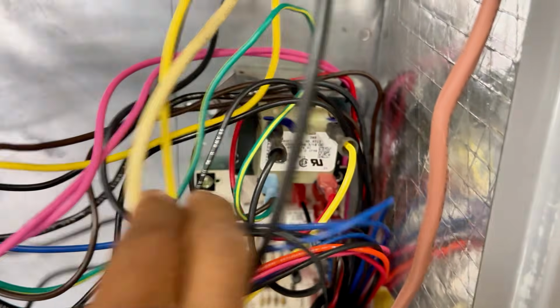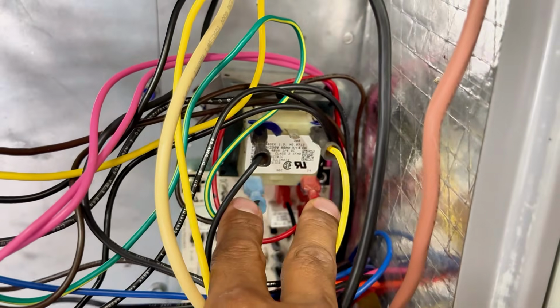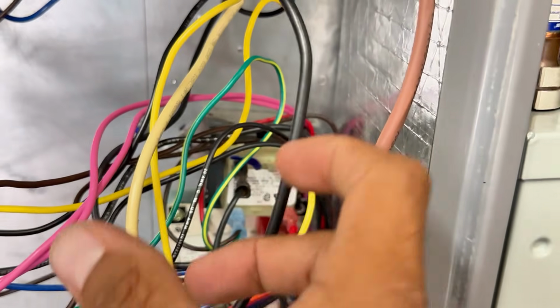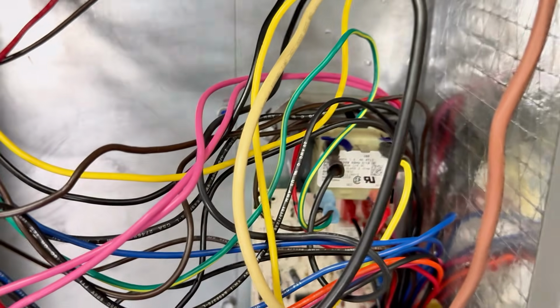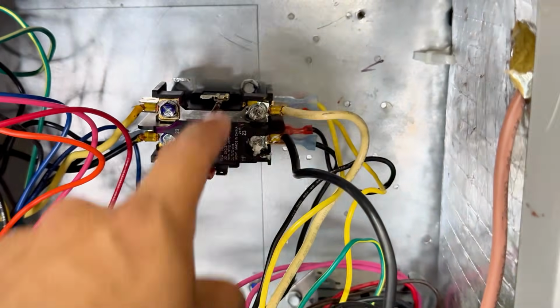Yep, you got a red wire coming out. If you look closely, I don't know if you can see it, but it says secondary right there, and that's 24 on the right. And this one on the left says C, common. Remember from the previous clips, we know that these two, when they come out, cannot touch each other. You got the Bloods and the Crips. They need to go to a load, something like the contactor coil.